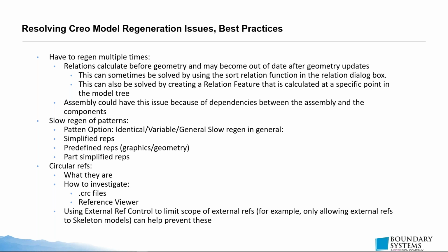So that's the loop that you can create. It actually creates a CRC file, which is basically a circular reference file, and I'll show that. And you can also use a reference viewer that shows you how these different features are referenced.